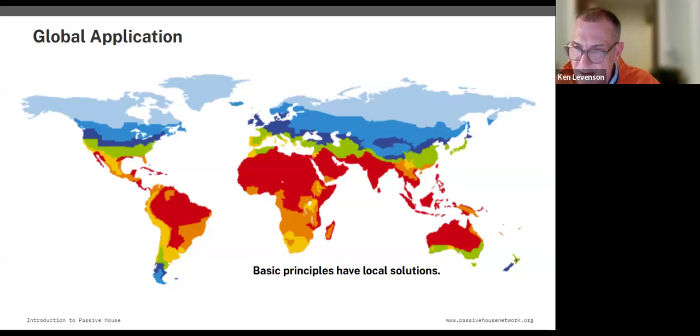Do the ductworks go through the attic or through the wall? They could go through either. It could go through the floor too. There are buildings where the ventilation unit could be in the cellar, or it could be on the ground floor and go out and around. The systems will use earth tubes to bring in the air and actually temper the air with the earth temperature before coming into the ventilation system in the cellar. So really anything's possible there.